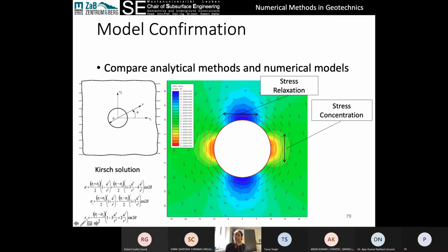So stress magnitude and stress orientation also need to be calibrated, and normally with observation. Now, of course, if we're in a green field and we don't have a tunnel to compare with, we have to be using different methods to do that. Maybe using another case study to validate our model, to calibrate our model, or using other experiments like modeling a UCS experiment to say, okay, yeah, my input parameters are the same as my lab results, so I can use those material properties in my model. So that's the calibration stage.